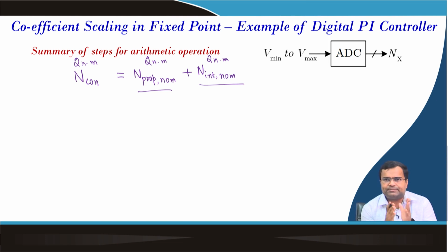So we have to make sure, because if we add two binary signed numbers, say 4-bit, and both are positive, then there is a possibility of overflow, and you have to detect that. With signed numbers you have to be very careful about wrapping error. If both are negative, there also you have to check. Otherwise, if they have alternate signs or are not maximum values, you may not have any overflow.